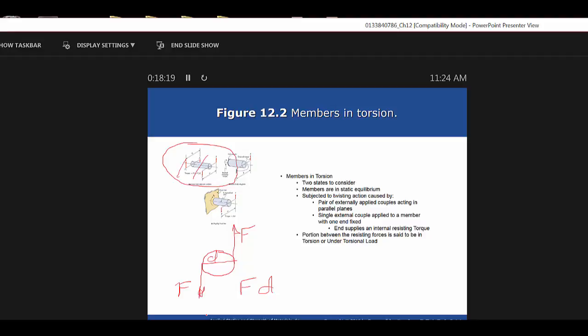Okay? So, expressed in pounds inches, pounds feet, Newton meters. If we were converting pound inches to pound feet, times 12. Or it's either divide or multiply, let's see. Keep in mind that is pounds times inches, right? That's what that little dot in there means, pounds inches or pounds feet. You have 12 inches in 1 foot, so you'd be dividing it. Okay? And then you'd be at pounds feet.